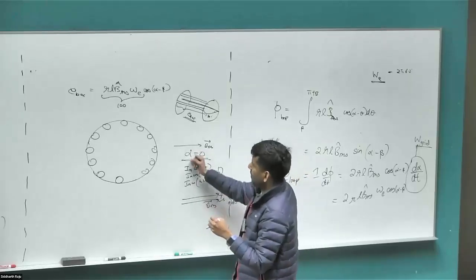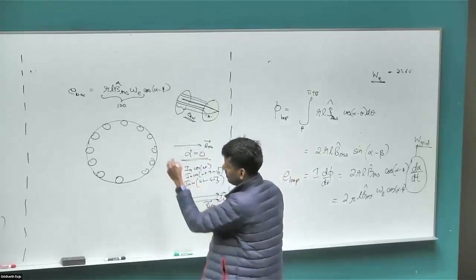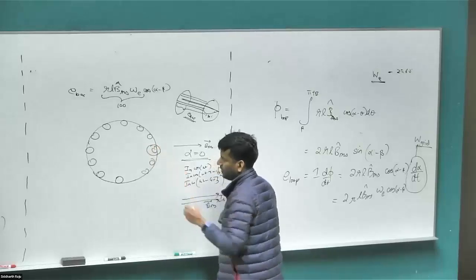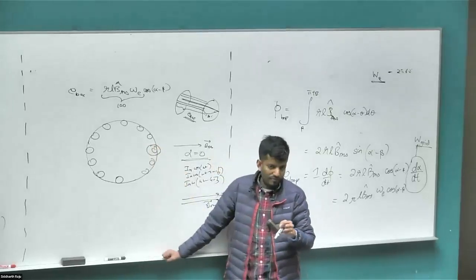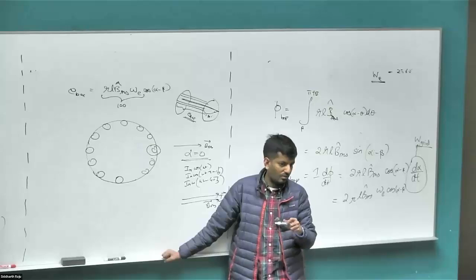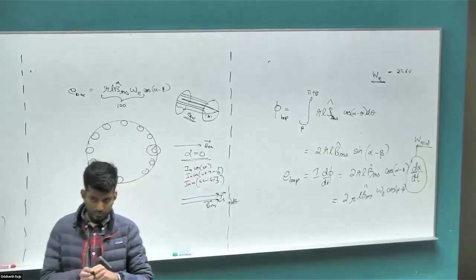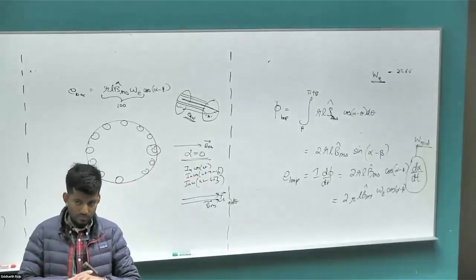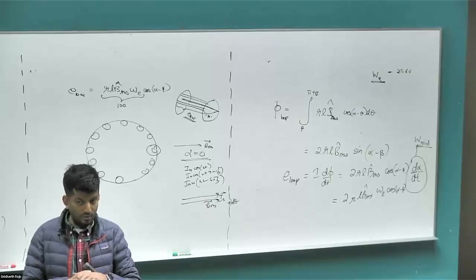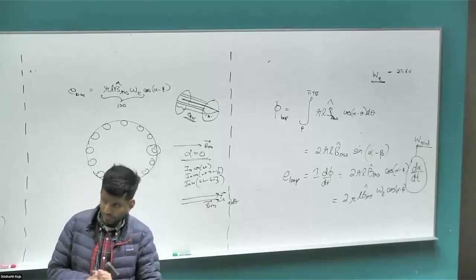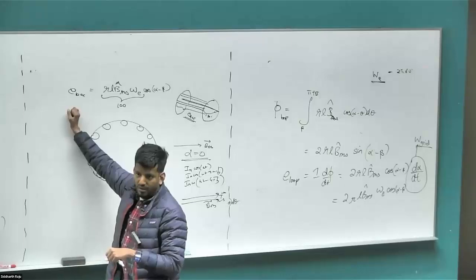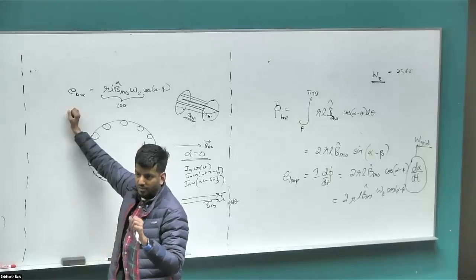Okay. So now if alpha is equal to 0, what will be the voltage of this bar right here? What will be the EMF across that bar? 100. Yeah, sorry. The currents in the bars, are those induced by the stator? There is no current yet. We are not talking about currents in the bar at all yet. We're only talking about the EMF induced across the bar. So you can assume the bar has infinite resistance.